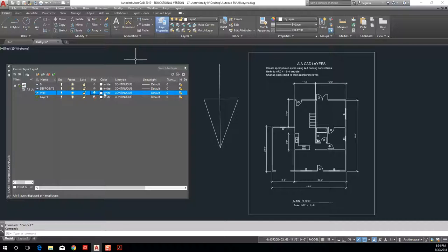Okay, so we have our print, non-printable. This functionality is going to be useful for a printing option that we'll talk about in a week or two, right? Then we have our color, okay? The color is what assigns a pen weight or a line weight to your lines. These colors make your lines thick or thin, all right?